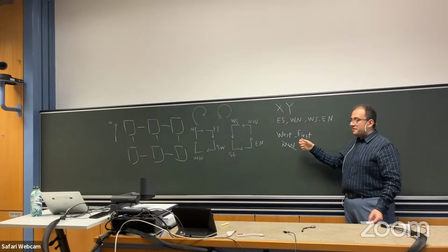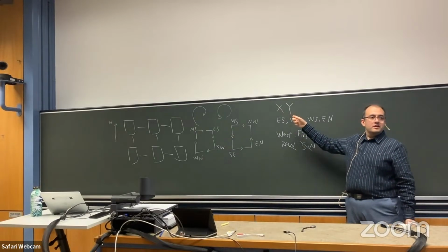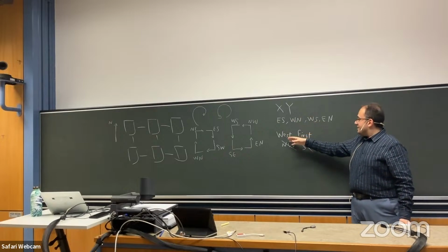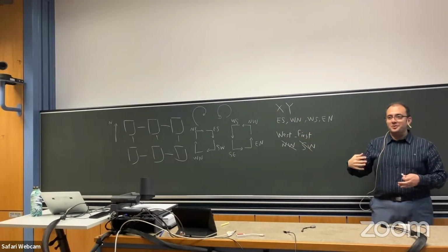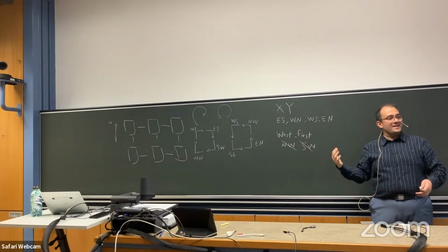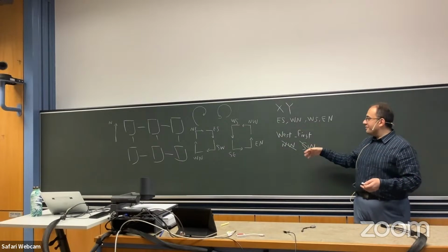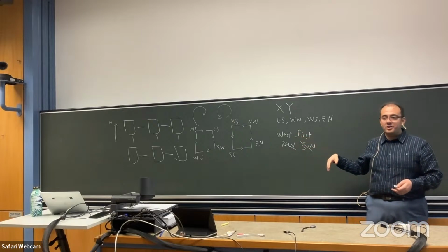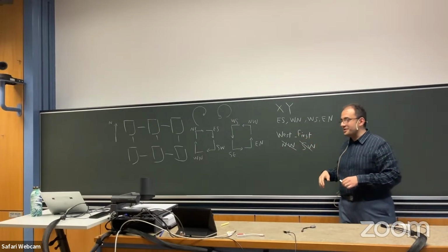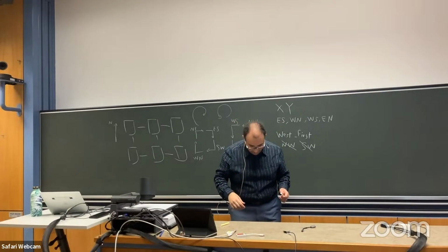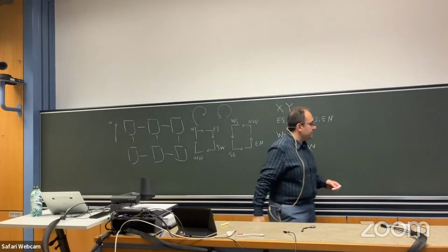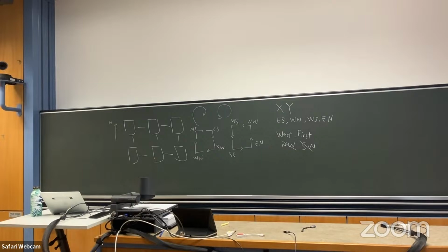And actually, the performance of west-first is better than XY. But the issue is that west-first is not balanced. If you go west, you are deterministic, and if you go east, you are adaptive. So people have also come up with many other variants, like odd-even. You can search if you're interested. Those provide better adaptivity. Any question?